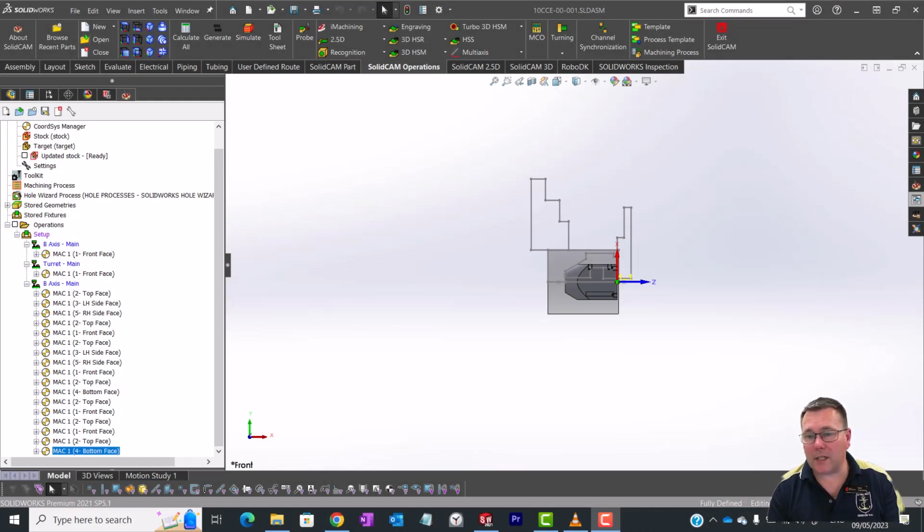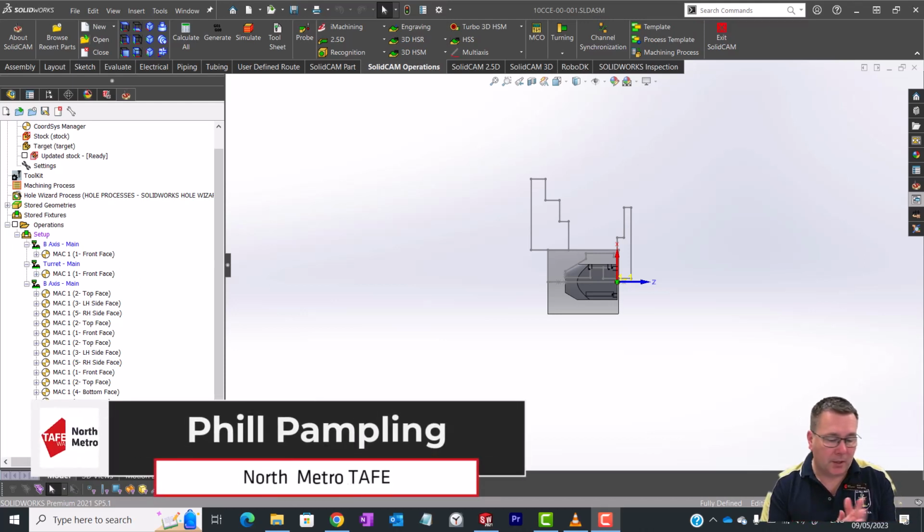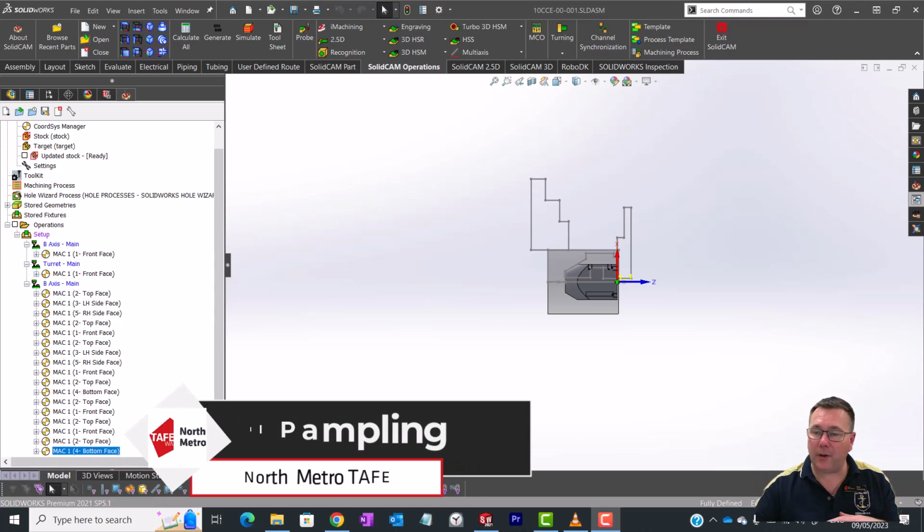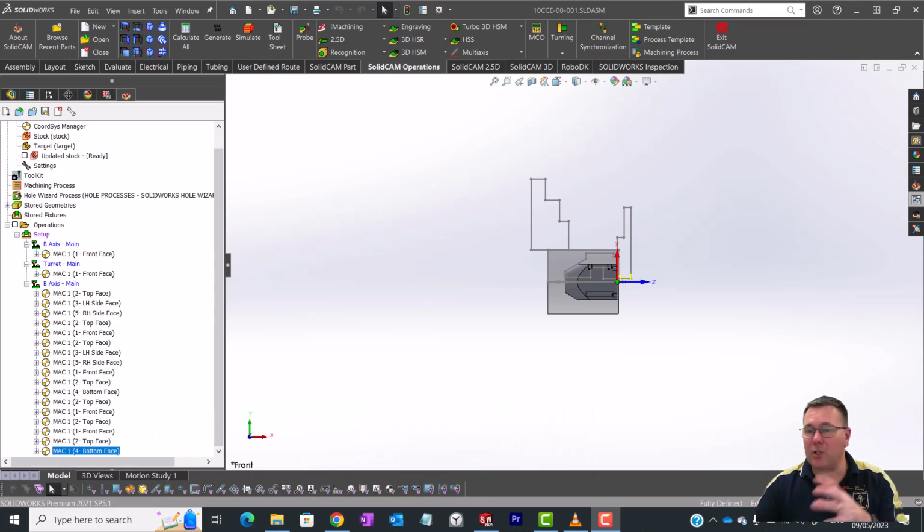Alright, and welcome to this lesson on conducting a spindle transfer. So now that we've completed all the machining on the back part of our component, we want to bring the sub spindle up, grab hold of it and transfer it to that sub spindle so we can machine that front nose of our component.